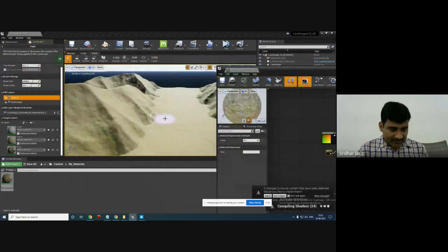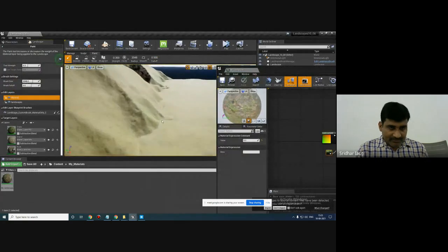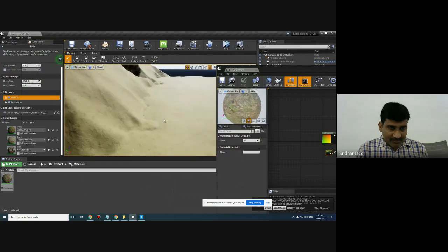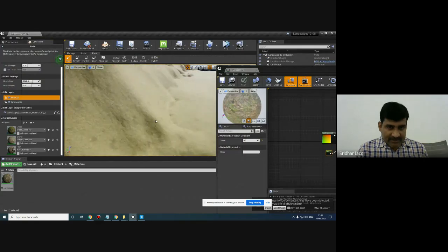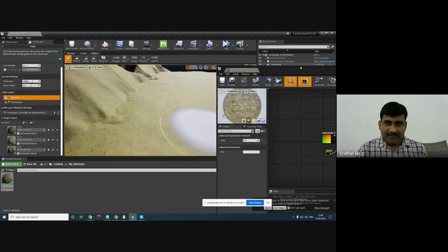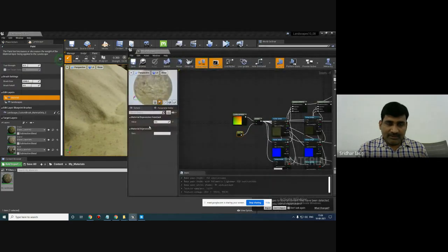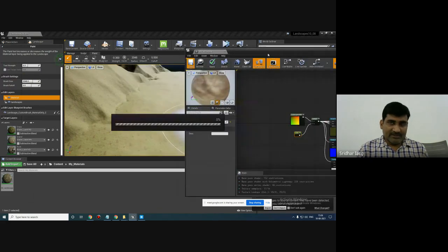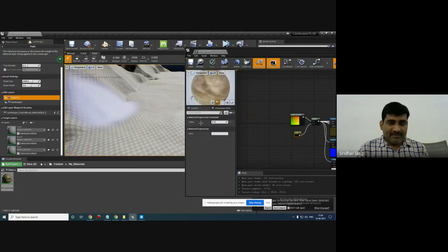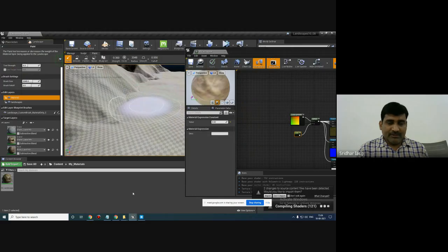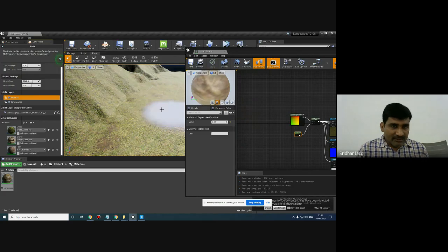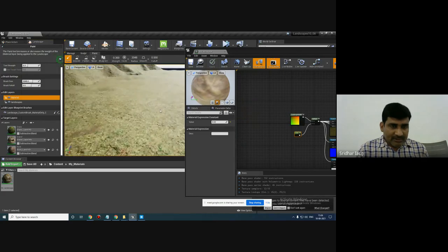So now you can see the difference here. Okay. Still it is looking very small, right? If you want to increase it more, then you have to decrease the texture scale lower, 0.02. We had given 0.2, right? Now we are applying 0.02. Depending on the map, it will change the scaling, right? I just used all the 8K maps, which are exported from the grids, right? So I think now it's looking good actually.